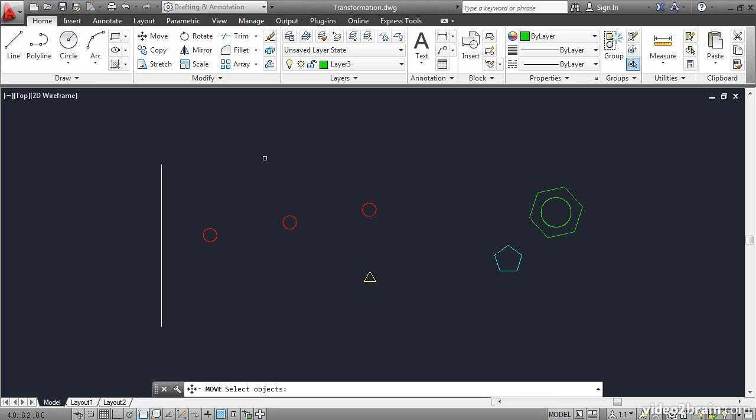Of course, another way you can move objects is using a measurement. I'll move the previous object. I'll type P, Enter, press Enter again, and then I'll click some arbitrary point. Take care not to click a point that snaps to an object. When I say arbitrary point, I mean to move the cursor away from the other objects on the screen so that snap doesn't interfere with your selection. So I'll click some point, and then I'll type in a distance on the keyboard. I'll type @5,0, so I can move it 5 units over horizontally using Cartesian coordinates.